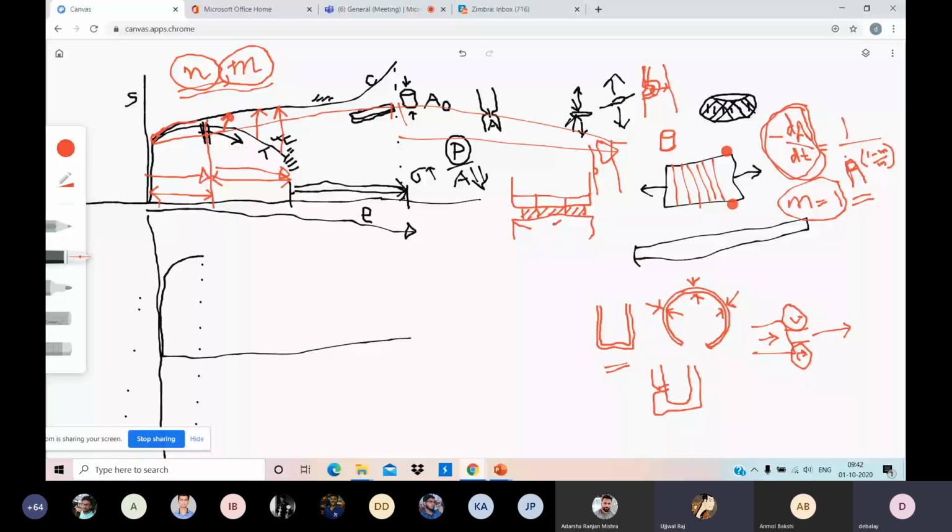For the metal to flow this side in compression, there is a resistance at the interface, and against that the metal has to flow because the metal is continuously in touch with the platens. So if it has to flow, what does it have to do? It has to work against the friction generated at the interface.